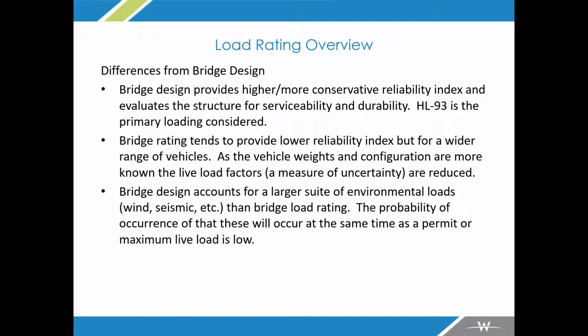Bridge design can also account for environmental loads, wind, seismic, all that kind of stuff that load rating typically doesn't. The main thing is it's a probabilistic problem: are you really going to have the worst case loading you've ever had on the structure at the same exact time as an extreme event like an earthquake? Very unlikely to happen. So we don't usually design for that or load rate for that, because it is such a low probability event that those might happen at the same time. So again, a little lower on the environmental loads, really focusing on the live load, dead load, DW, depending on what your state's guidance is, or general governing authority, I should say, maybe your province or wherever else.